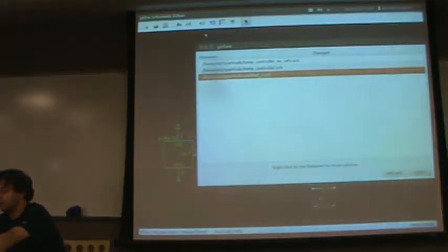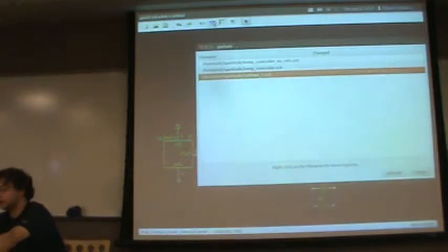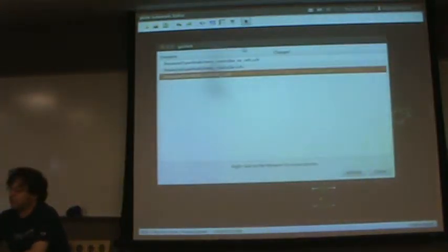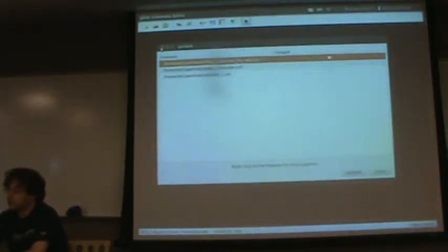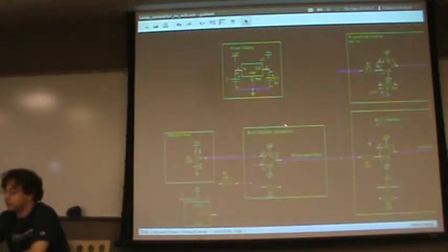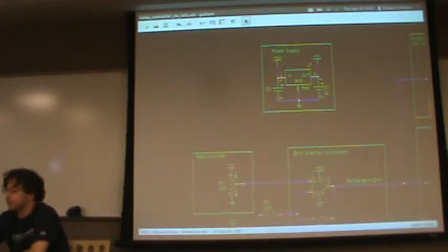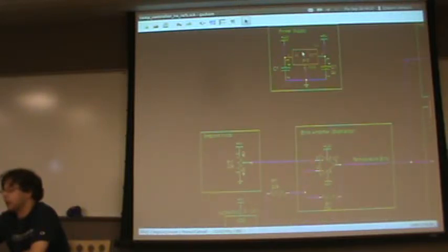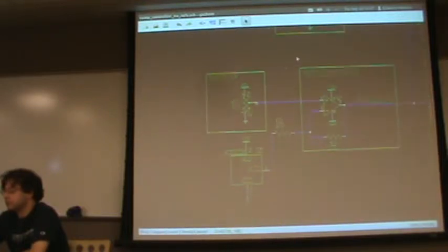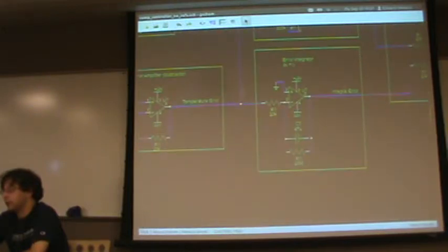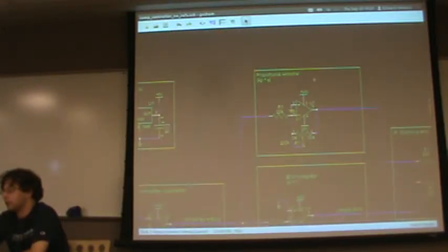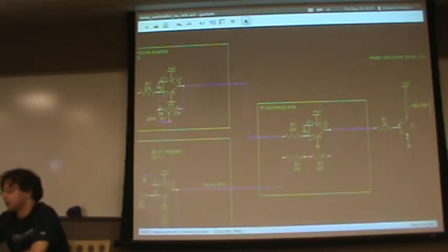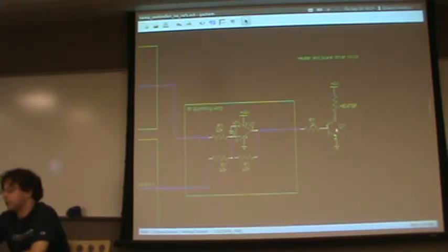If you go up into the menus up here, there's a page manager, and that shows all of the things you've got open right now. And I made this earlier, so just go through really quickly. Here's just a 12 volt to 5 volt power supply. It's a 7805 power regulator, a couple capacitors, and then this is the part that I already showed you. Here's my integrator. Here's proportional amplifier, summing, heater controlled by a transistor.